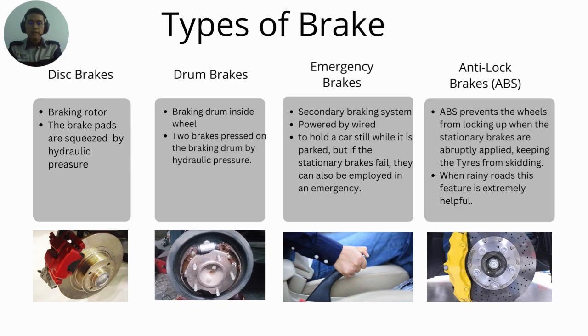After that, the drum brakes. It works by mounting a braking drum inside the wheel. Two brake shoes are pressed on the braking drum by hydraulic pressure as the brake pedal contracts. And then the emergency brakes.